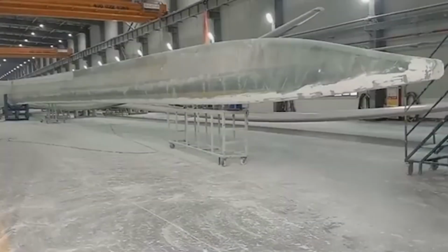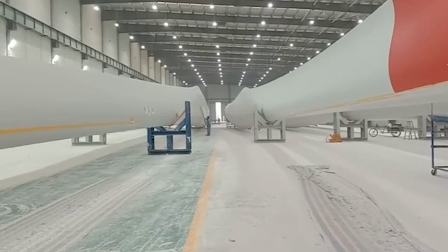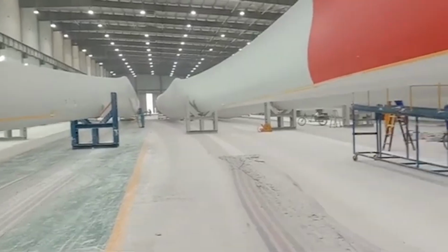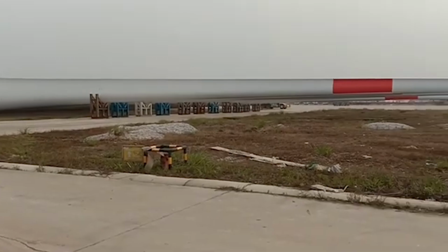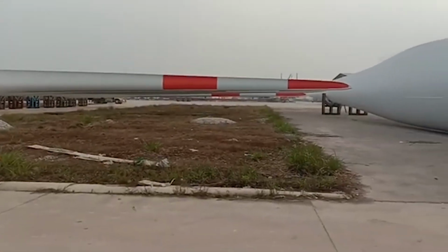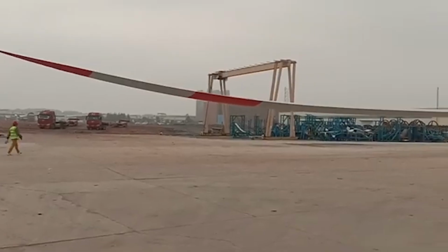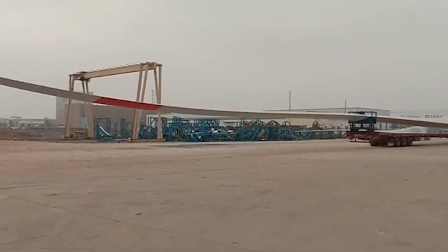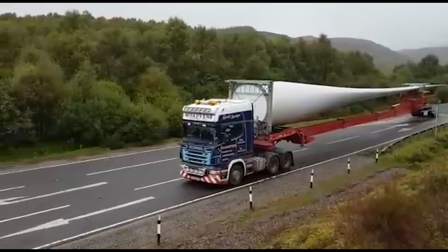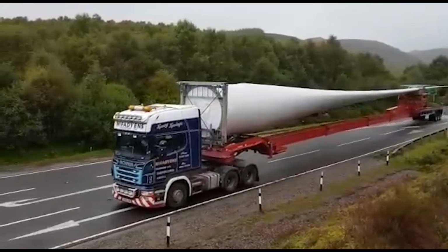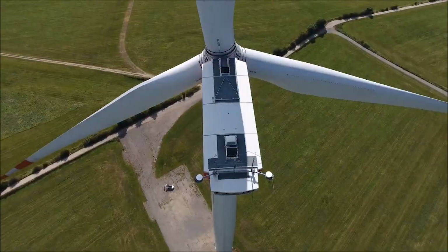Blades are usually fabricated from thin-walled fiber composite materials, with fiberglass reinforced polyester or epoxy. Carbon fiber or Kevlar is also used as reinforcement material. Carbon fiber has more tensile strength, higher stiffness, and lower density than glass fiber. It is also 20% to 30% lighter than glass fibers, leading to thinner, stiffer, and lighter blades. However, glass fiber is more commonly used due to its affordability.